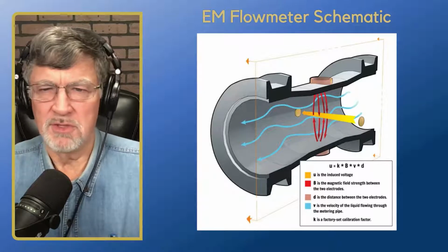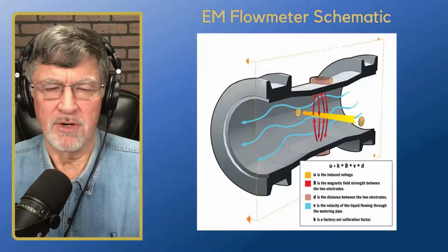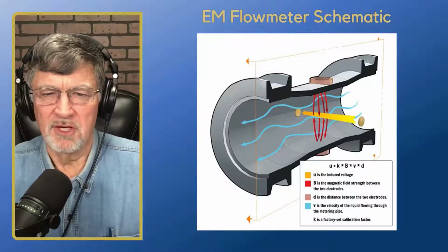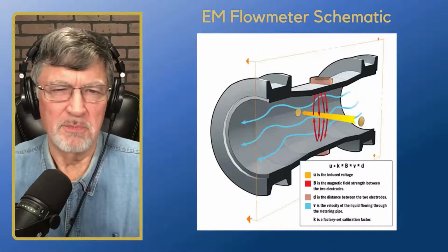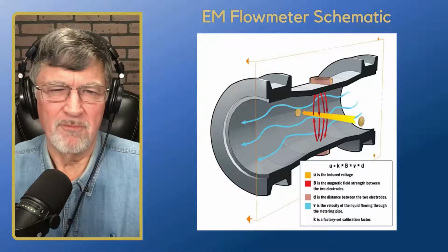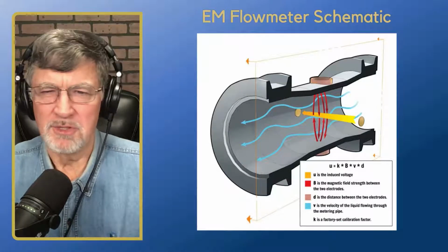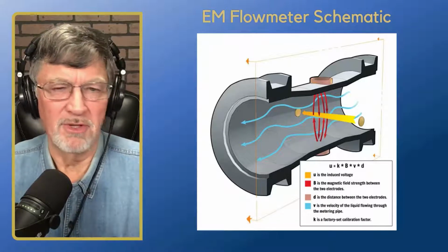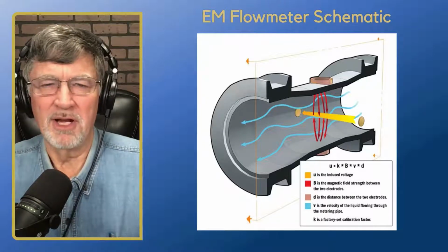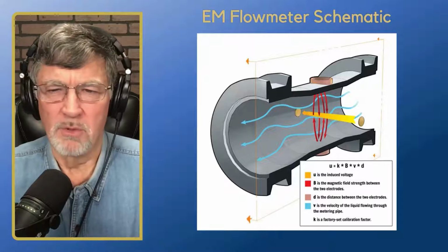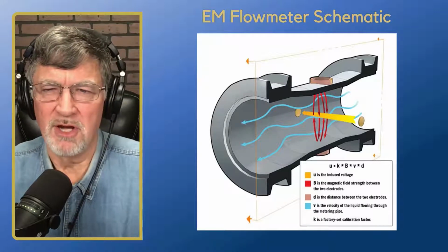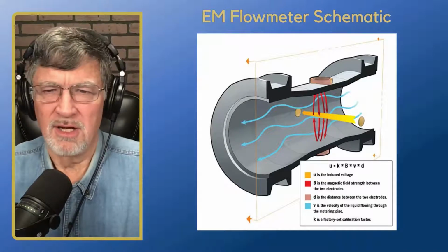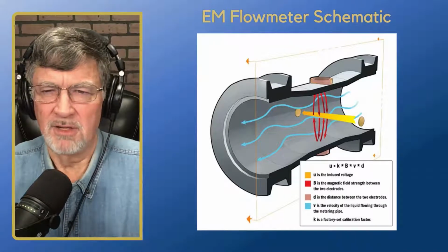This once again is showing how it operates according to Faraday's law of induction, and so this is kind of an example of a flow meter that you'd put on your pipe from your pump to your distribution system to totalize your flow or to see what your flow is. The electromagnetic flow meter works the same way going down the well. So it's using water as the conductor, and it's measuring the inductance across the flow profile.